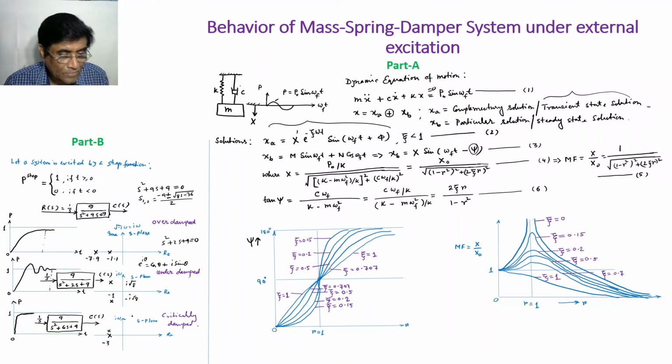And then of course I have another, critically damped situation. Critically damped situation is very good. See, s square plus 6s plus 9 equal to 0. When this is equal to 0, you will see that the two roots are overlapping each other, negative definite, and that ensures that the response is like this. So what does it mean? You see, the transient state is very small here. Means this is very good. Why is it very good?